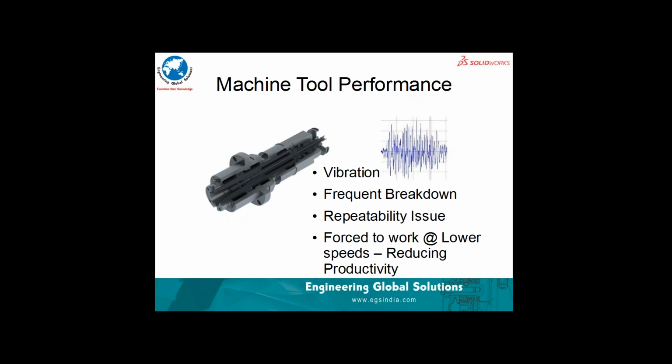After we have fabricated, put it together, we will be going and checking the vibrations at the bearing locations. Why not do it at the design stage? By doing a simple analysis which is called a frequency response analysis. Without doing it, the vibrations would not be under control. The product repeatability would not be under control because we do not know which are the tolerances which are sensitive.